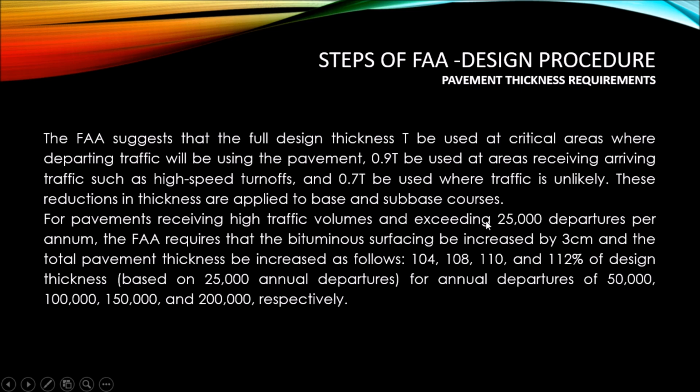For pavements receiving high traffic volume and exceeding 25,000 departures per annum, the FAA requires that the bituminous surfacing be increased by 3 centimeters and the total pavement thickness be increased to 104, 108, 110, and 111% of the design thickness based on 25,000 annual departures, for annual departures of 50,000, 100,000, 150,000, and 200,000 respectively.